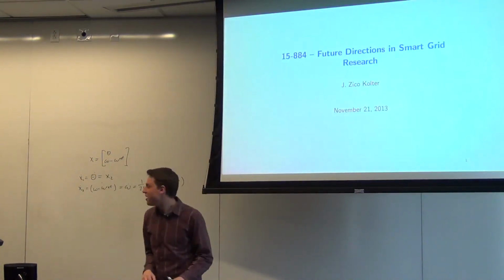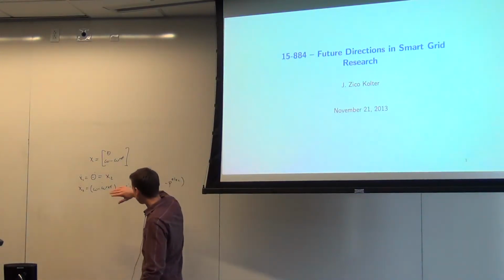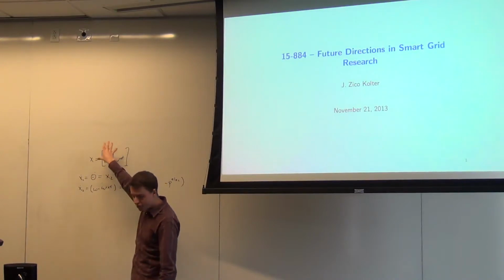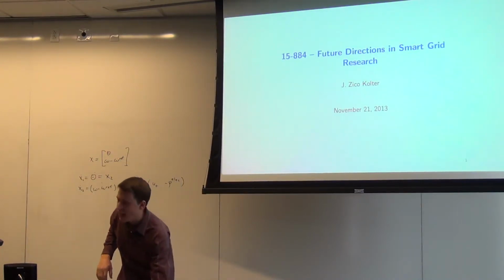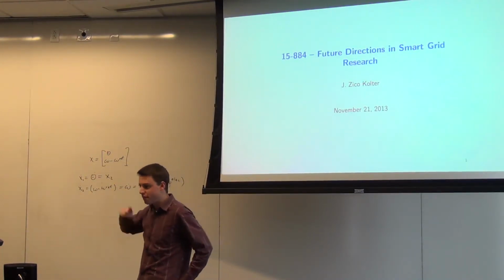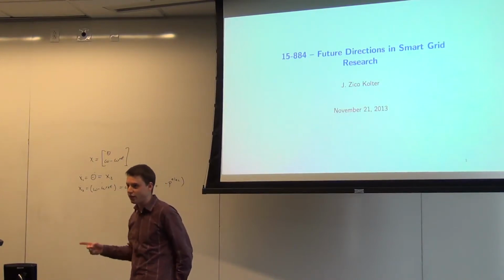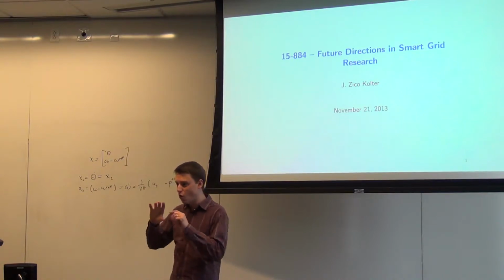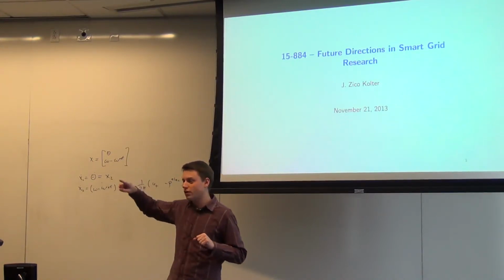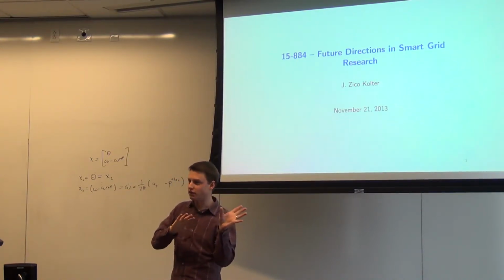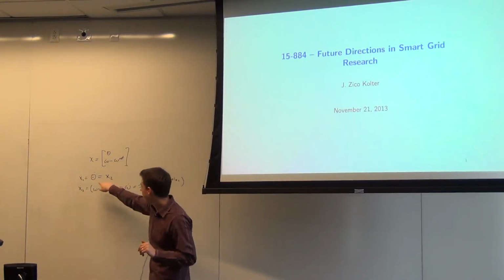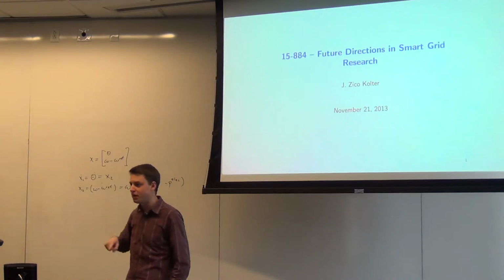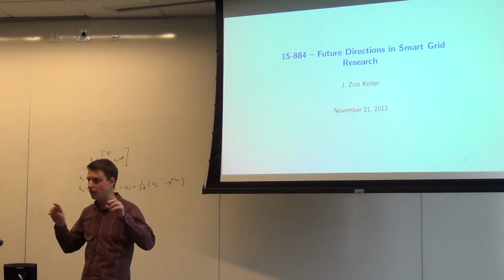There we go. So I didn't want you to have to worry about what omega ref was, but the important part is theta. If you think about the angle of a generator, well, this generator itself is spinning many times a second, right? But we don't care about the absolute angle of that. What we care about is where this angle is relative to everyone else's angle. And so theta is a deviation from where it should be in some globally synchronized rotation.